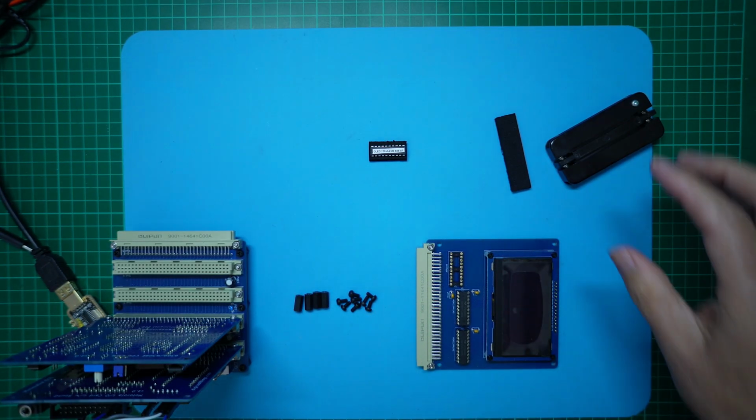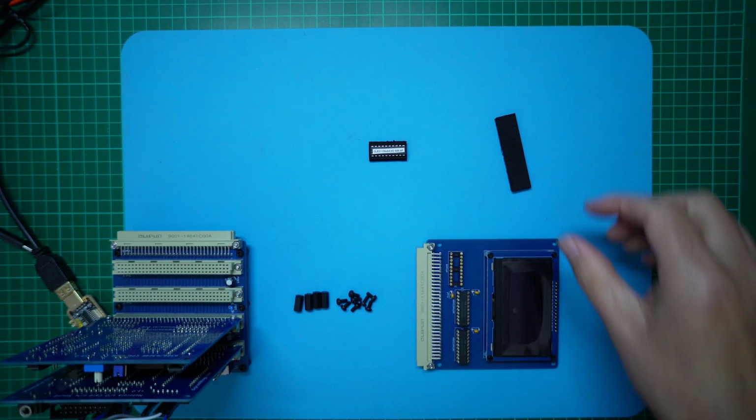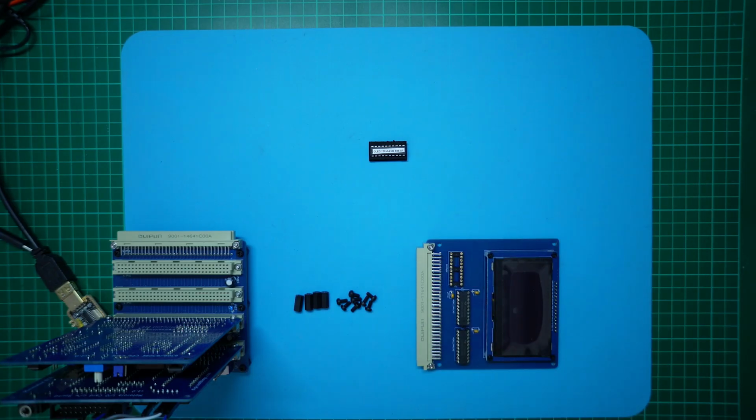Finally, we have the PLD for our address decoding. I've chosen to locate the OLED display card at IO address block 88 to 8F, being just above the 80 to 87 that I previously allocated to my VDP display cards. These different display cards can therefore happily coexist in an MECB system.